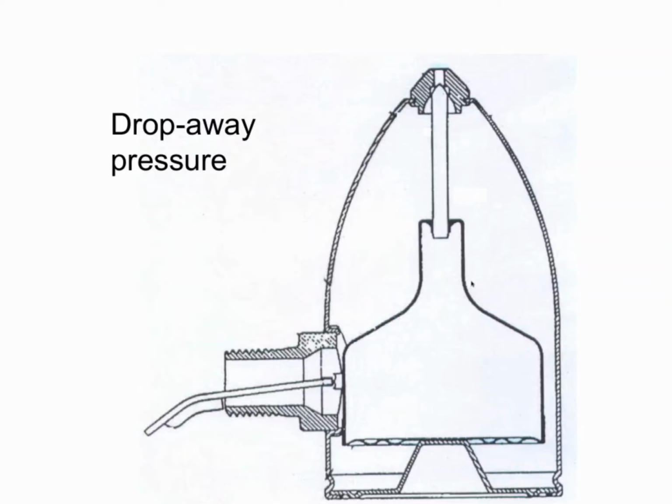What I will say is this particular vent, there's two places that you'll see this particular vent. Usually on a self-standing cast iron radiator or even a cast iron element, also known as a cast iron convector. And I'm talking about the older cast iron elements that were made years ago. I think they're called ahk or RO. These are no longer even made.